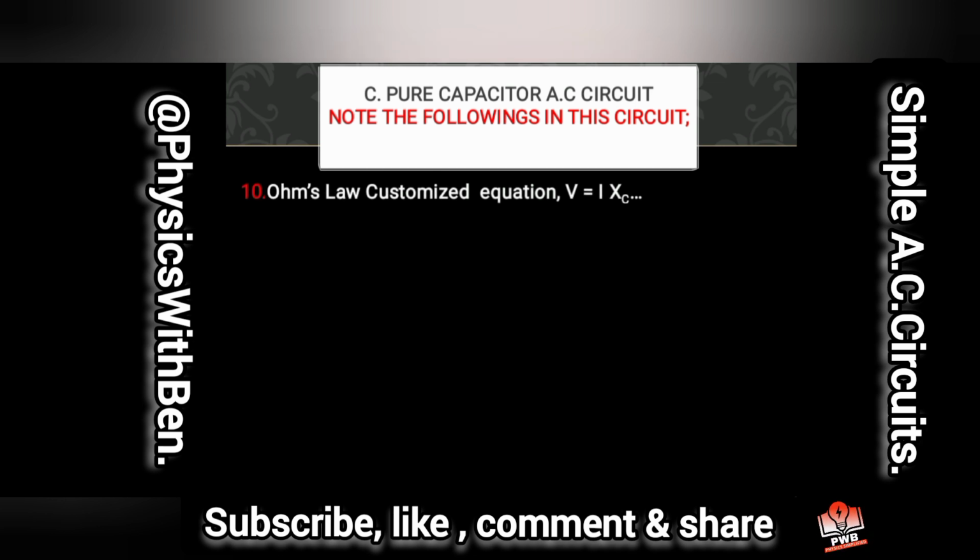Next up, the Ohm's law equation, which was written as V = IR, is now customized into V = I XC, where XC is the capacitive reactance. The capacitive reactance and the resistor are measured in the same unit of ohms, since both of them do the work of opposing the flow of current. So this is the customized Ohm's law equation.